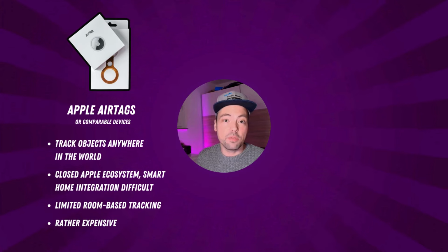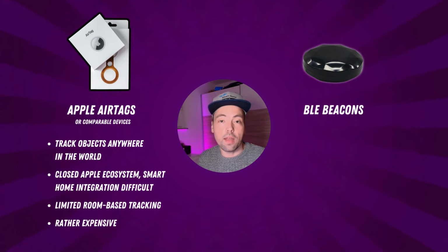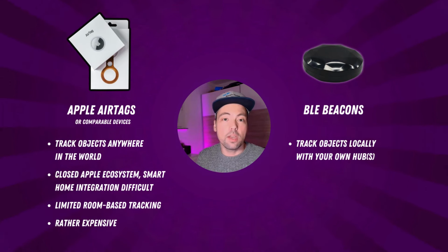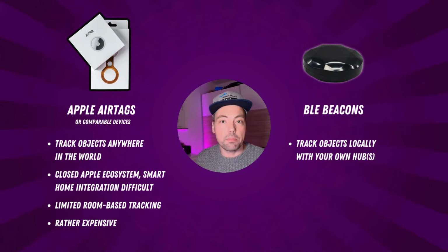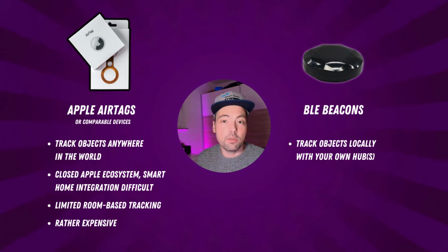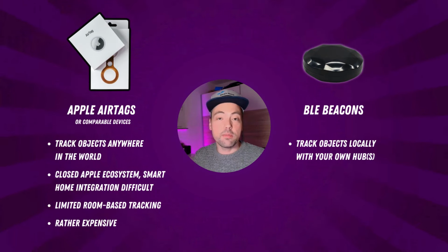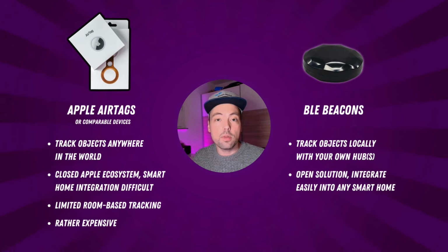Another option I see for this use case are Bluetooth Low Energy beacons, or BLE beacons. Those are also usually rather small devices that allow you to track them via Bluetooth. And with this, you can create your own tracking method within your house with your own hub or hubs. That means you can create a hub which tracks all the objects around, and you can place multiple of those hubs in and around your house, and this helps you to identify whether an object is closer to hub number 1 or hub number 2, and with this you can identify in which actual room of your house those beacons are at the moment.